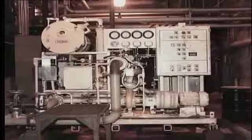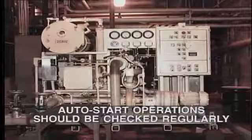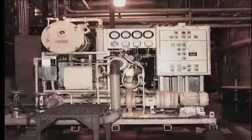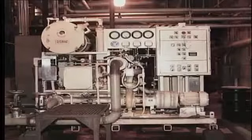As with all automatic devices, the pump auto start operations should be checked on all pumps regularly. Make sure that you check out the details of your own lube oil and hydraulic oil systems. You should be thoroughly familiar with the location of all pumps and controls for these pumps. Now at this point, let's take a break, and then we'll come back and take a look at vacuum equipment on the turbine. For now, please switch off the tape and review this material in your workbook.